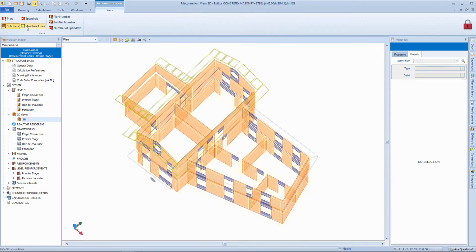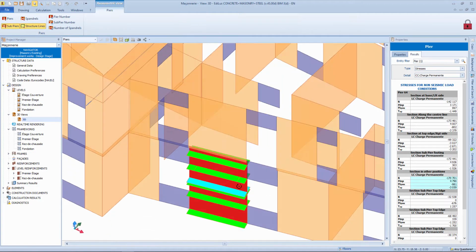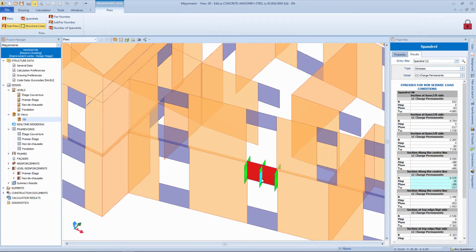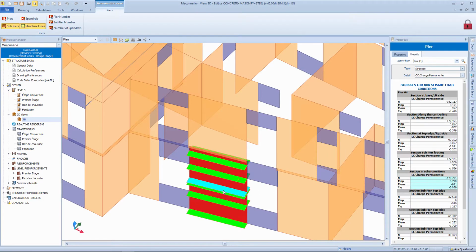Accessing this view of the model and selecting the piers, we notice the presence of horizontal sections. When we select the bands, we see the presence of vertical sections. Earlier we said that the shell model involves a calculation of the tensions, defined for the bands and piers. Horizontal and vertical sections represent these stresses and general stresses such as bending moments, shear, and normal forces. Then by selecting the elements in the model we will obtain the verifications required by the norm.